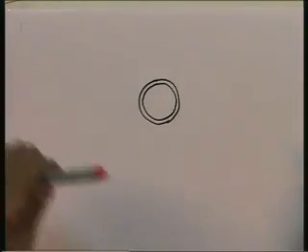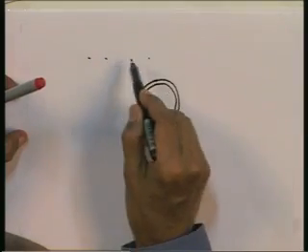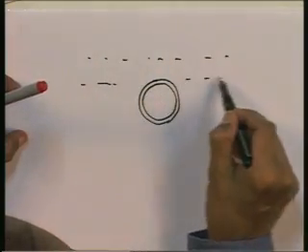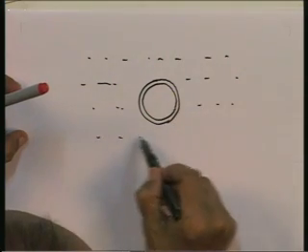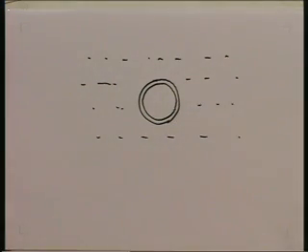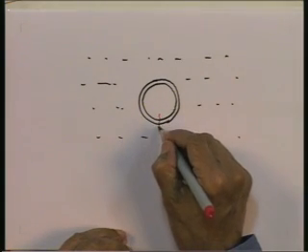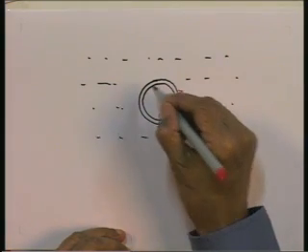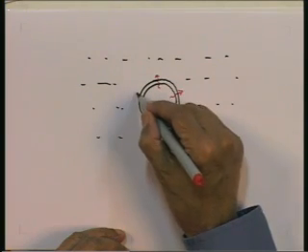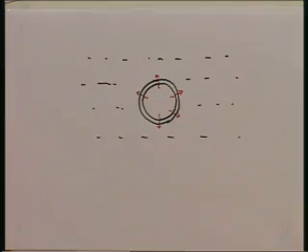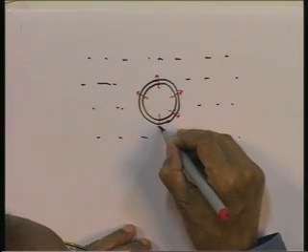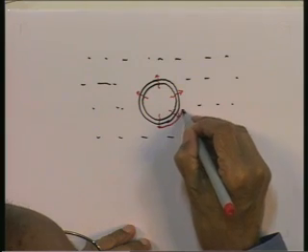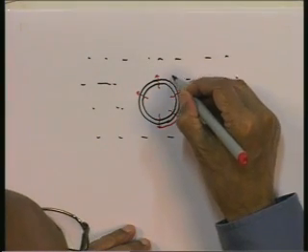Let us say this is a horizontal tube sitting in a pool of liquid. Heat is being supplied like this to the pool of liquid, and the temperature difference is large enough that we have got stable film boiling. So, what will happen? You will get a film of vapor all around that tube. Let me draw a film, with an exaggerated thickness again.